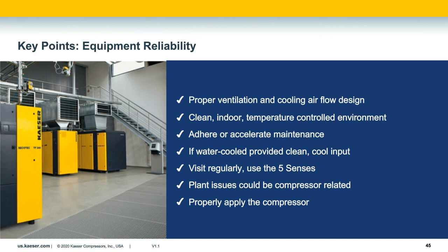Don't forget about your cooling water system or your sub-supply systems to your compressed air station. Visit the room regularly, or if you have a camera, you can check in. And then designing flexibility into your compressed air system is going to help ensure your compressors are properly applied and therefore reliable.